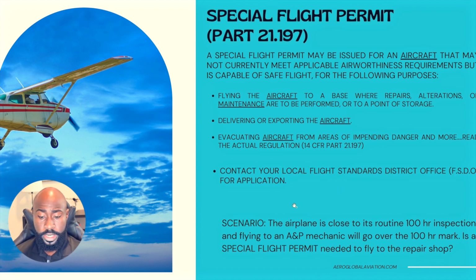I just put a scenario here to help us think about the different situations where you may need to obtain a special flight permit. The scenario basically says the airplane is close to its routine 100-hour inspection that we talked about earlier, and flying to an A&P mechanic will go over the 100-hour mark. So is a special flight permit needed to fly to the repair shop? As you can see, this is almost related to the very first reason I talked about, flying the aircraft to a base where repairs need to be made.